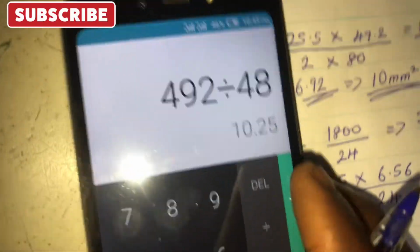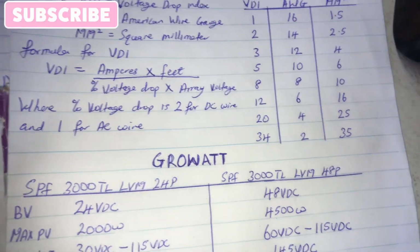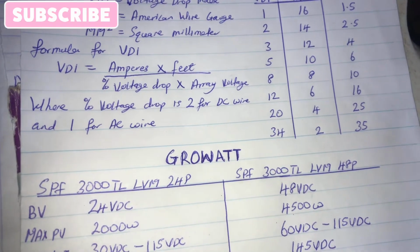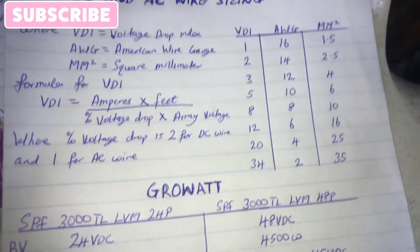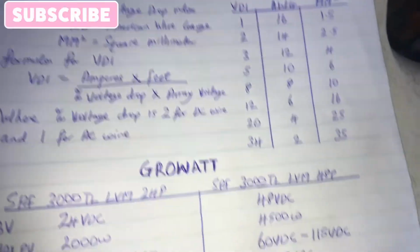So 10.25, going to our chart. There is no 10, there is no 11. What we have here is 12. So approximating it to the nearest whole number, which is 12, we have 6 AWG and then 16 millimeter square,